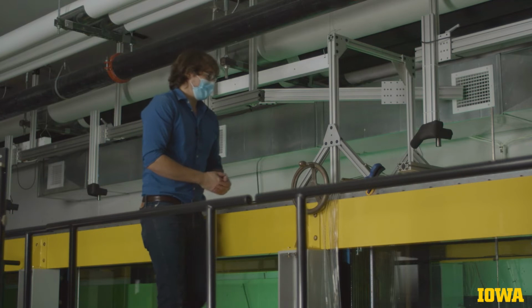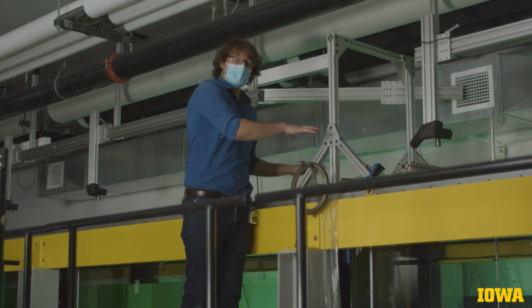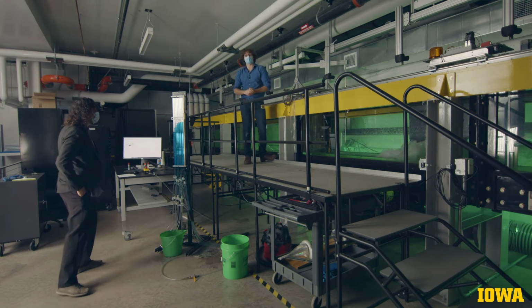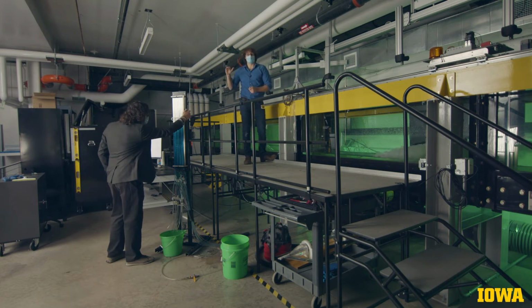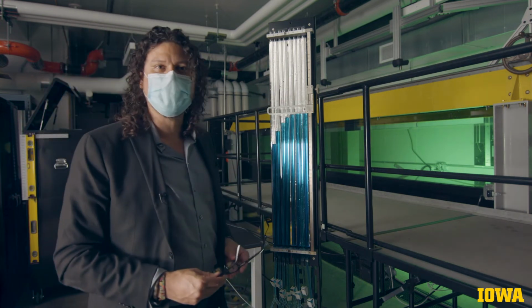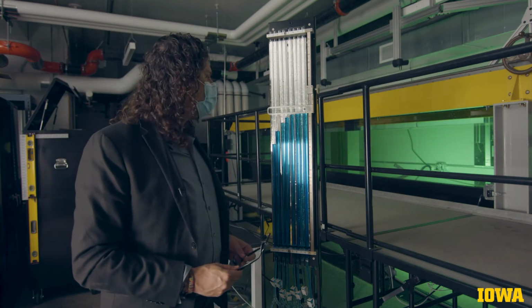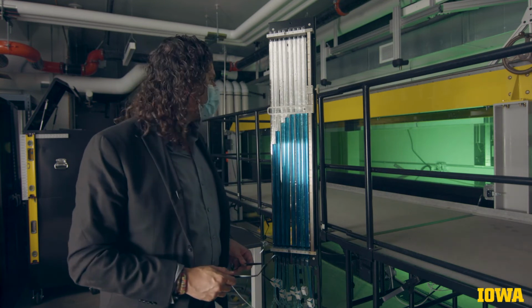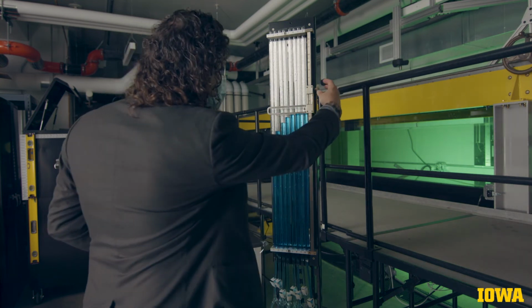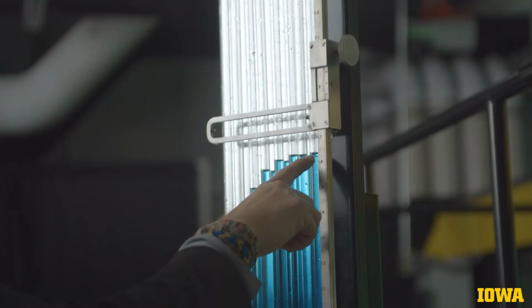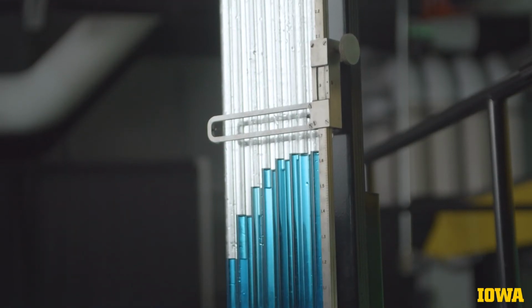To do so, we simply leave the sluice gate in its current configuration and use the elevation in each of the piezometers to measure the static pressure at that location, which will then be integrated using a trapezoid rule. So our manometers here are set up with a vernier scale that will allow us to measure the water elevation in feet with up to 3 significant digits of precision. So we're going to start making our measurements for tap 0, which is going to give us the total head of energy available.